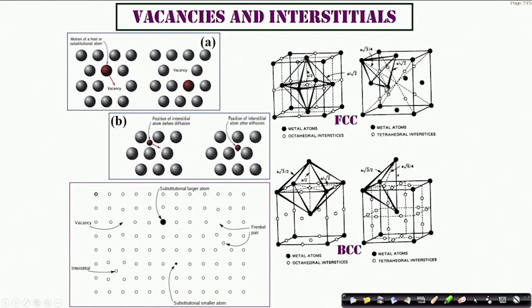And since this is geometric, where we can calculate exactly the length of these arms, we should also be able to calculate exactly the diameter of these vacant sites. So this kind of interstitial position, their size, their location can be geometrically determined using such considerations, both for FCC, BCC, and for that matter any other kind of Bravais lattices.